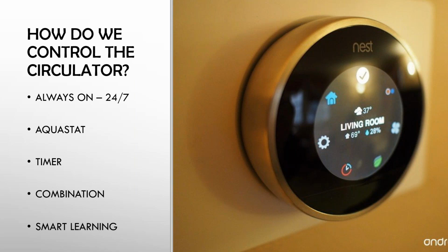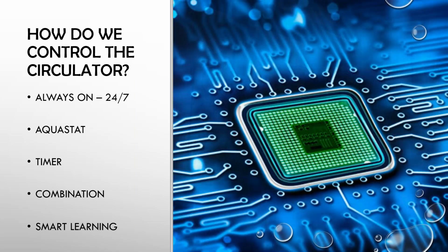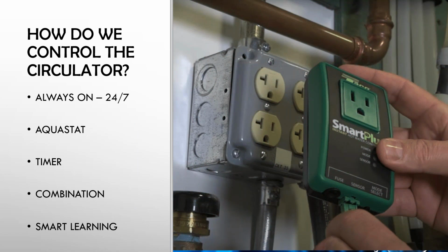So it's interesting when we start thinking about that. We took that learning technology, not necessarily with a motion sensor, and applied it to a domestic hot water recirculation style system. And we call it the smart plug. The smart plug learns when people use hot water in their home and will run the circulator for those time periods. It's always thirsty for knowledge and will always adjust your schedule as you are using hot water in your home. So now we have a smart system out there. It doesn't have an app, doesn't need to have an app. We just wanted to run the hot water circulation system.